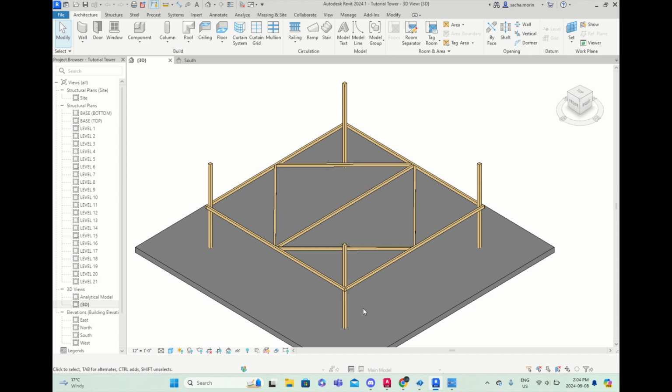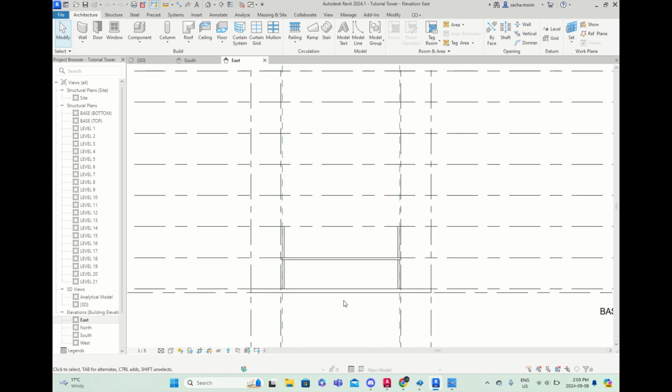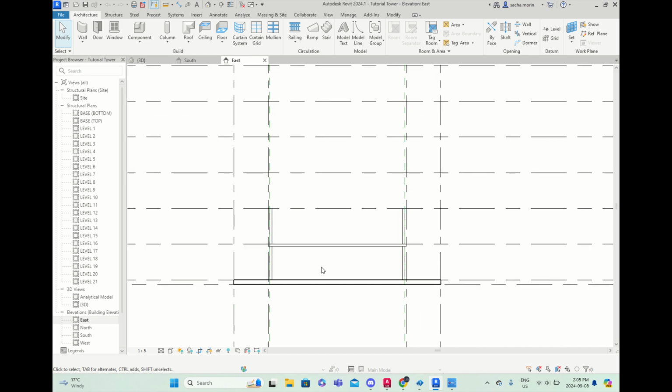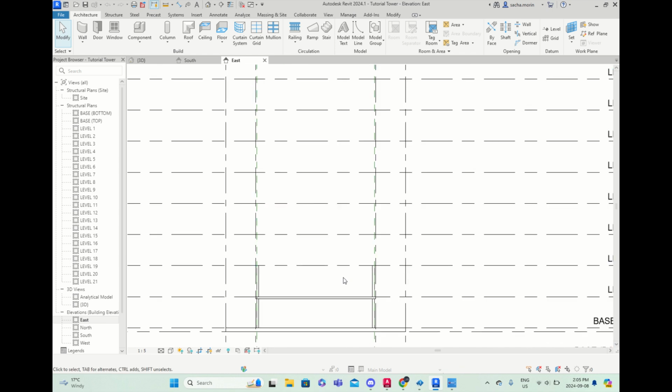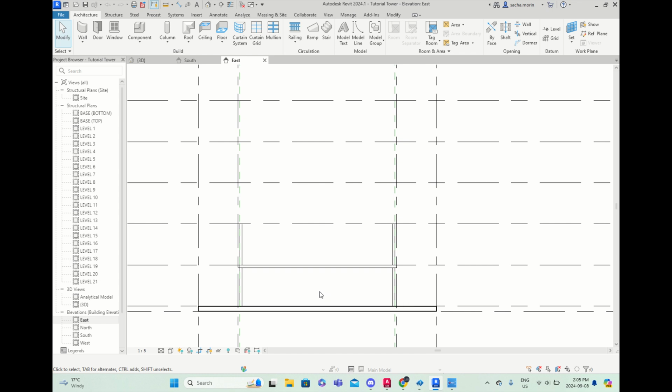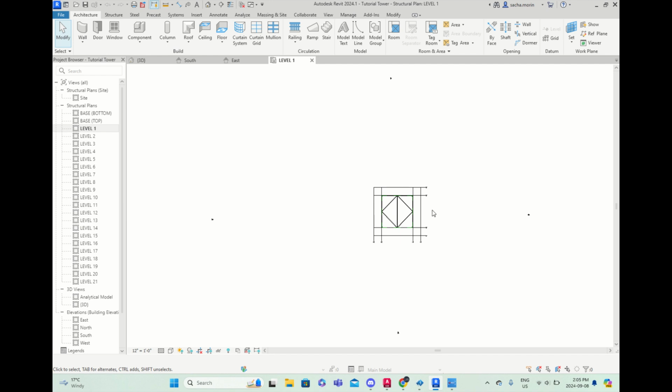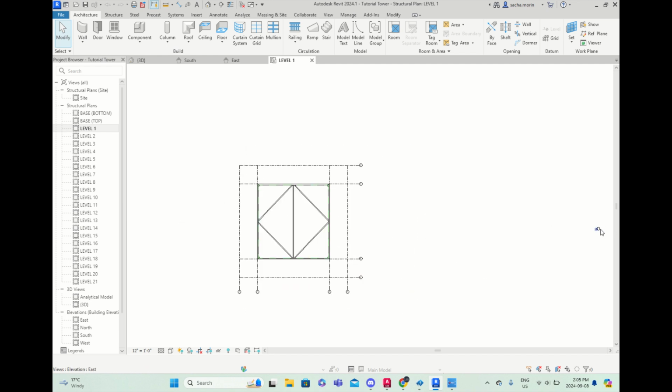But having that center line on, say, an east elevation is kind of hard to define, since the center of your brace will be in the plane not seen here. It'll kind of be in and outside of the page. So that means you have to make a grid line in one of your plan views that you'll be able to call when you're looking at that east elevation.